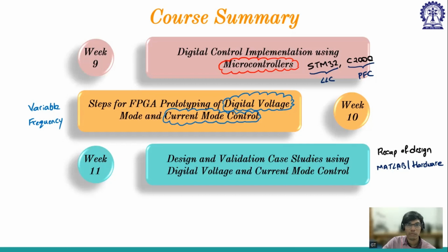Yes, to some extent, but we have also discussed it will not exactly match because there could be some parametric mismatch from the inductor value that we have selected and the actual inductor value. There will be tolerance limits. So there will always be some parametric mismatch, and there could be some unmodeled dynamics which we are not capturing and not including in the simulation. So we can use SPICE models with other software, and it could predict somewhat better than MATLAB, but it is again user choice. But MATLAB is sufficient and good enough.